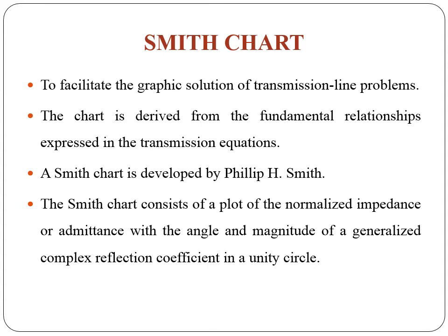The popular chart is developed by Philip H. Smith, known as the Smith chart. The chart consists of a plot of the normalized impedance or admittance with angle and magnitude of a generalized complex reflection coefficient in a unity circle.